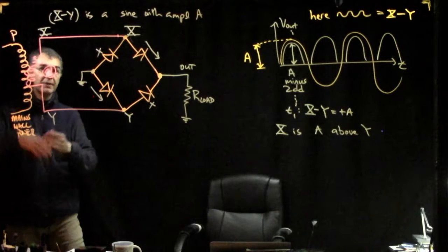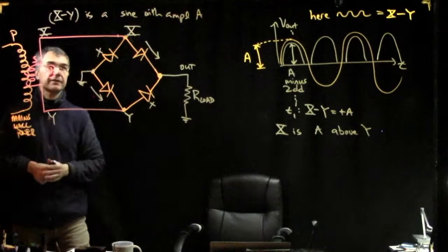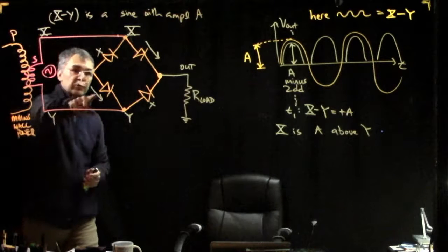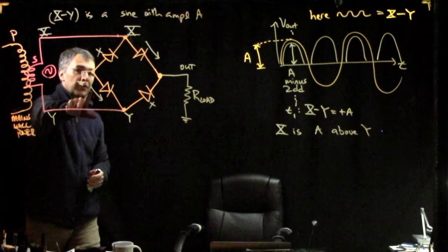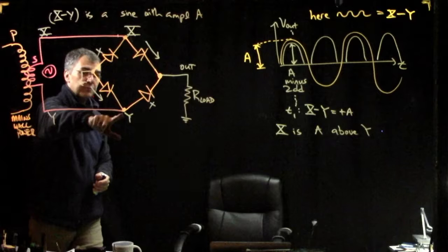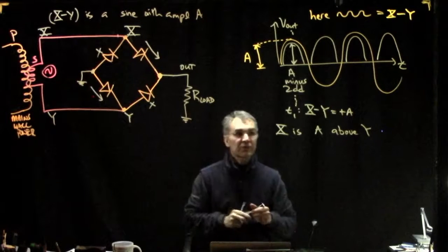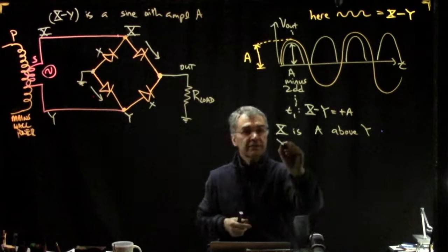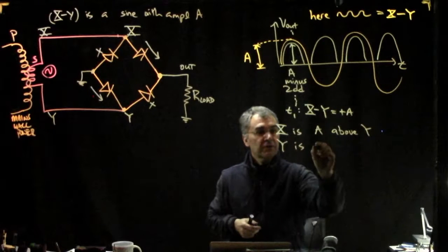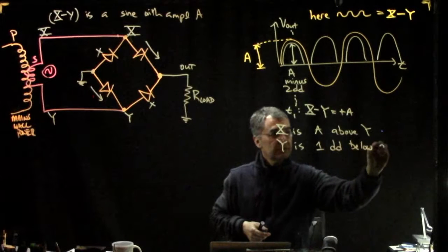Because we somehow need current to flow through the circuit between X and Y. So I guess the only other path is here, and that only works if this diode is on, and this diode can only be on if point Y is a diode drop below ground. So it seems like Y is one diode drop below ground.